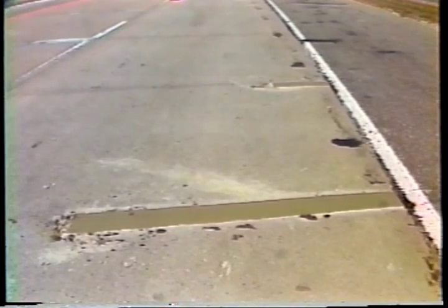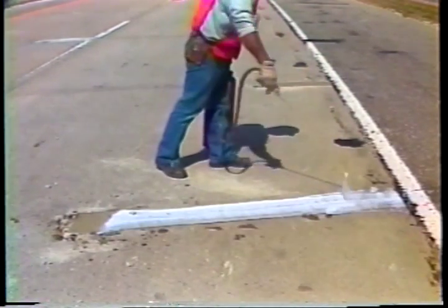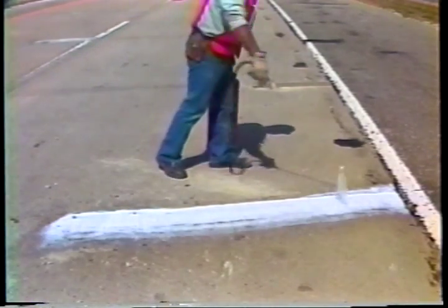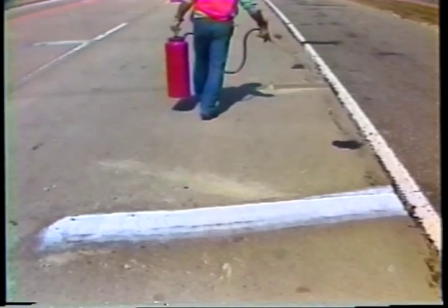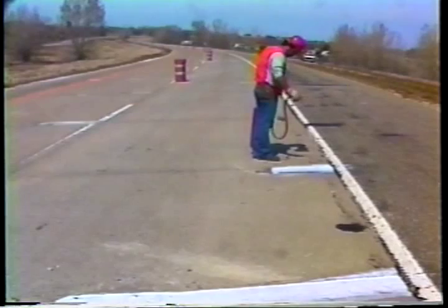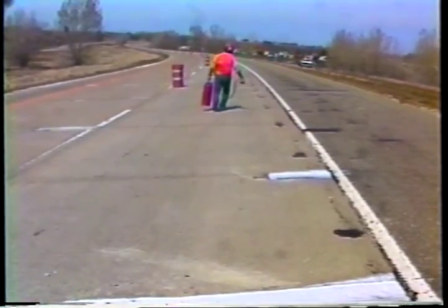Because these small repair areas have a high surface area to volume ratio, they lose moisture rapidly. So proper curing is very important to prevent shrinkage and premature failure. For proprietary materials, the curing procedure specified by the manufacturer should be followed. Best results with PCC have been obtained by applying curing compounds soon after the bleed water has evaporated. White pigmented curing compounds that reduce heat absorption while allowing the heat of hydration to escape are very useful in hot weather.